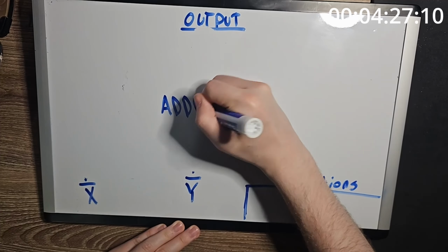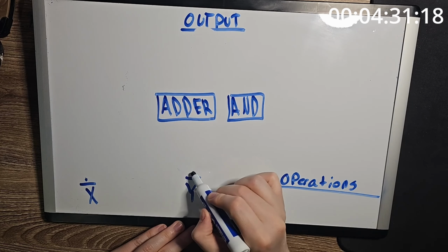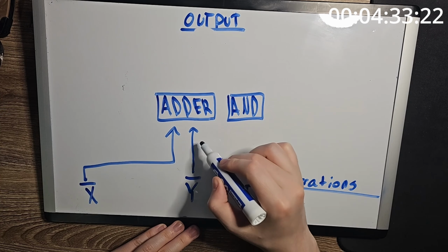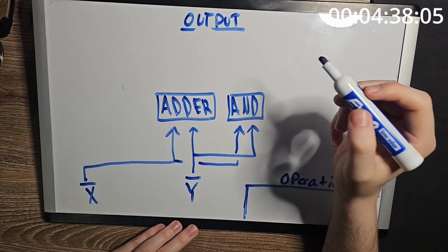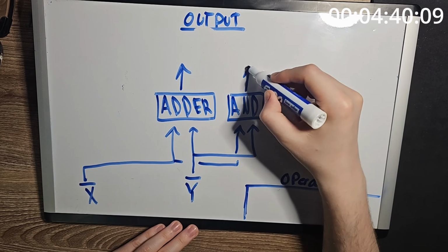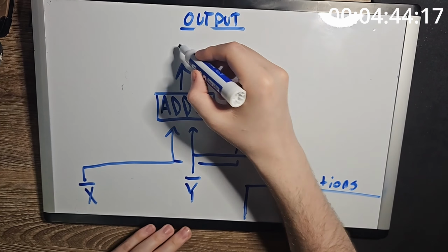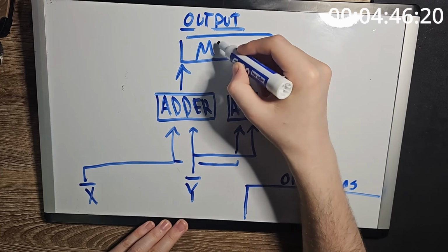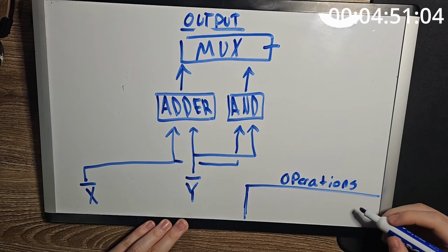This is just 16 AND gates lined up. This way we can compare X and Y. So now our ALU looks a little funky, and it is outputting 2 different operations. This is where our mux comes in. If we connect the output of both the AND and the adder to the inputs of the mux, we can then select whether or not we want to do one of those operations. So now our output is the mux's output.